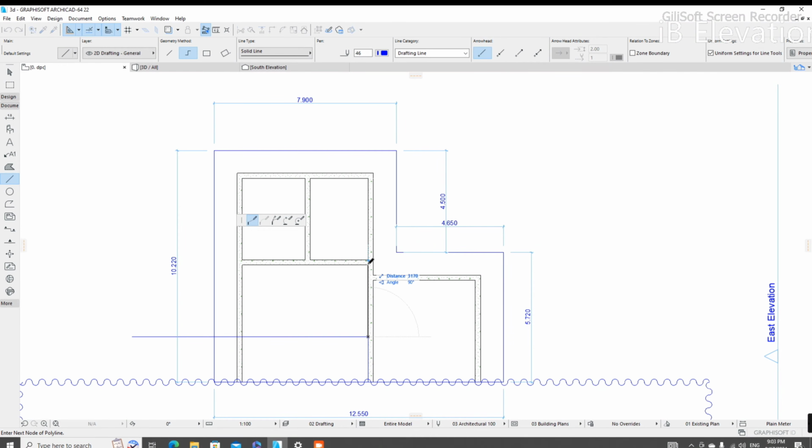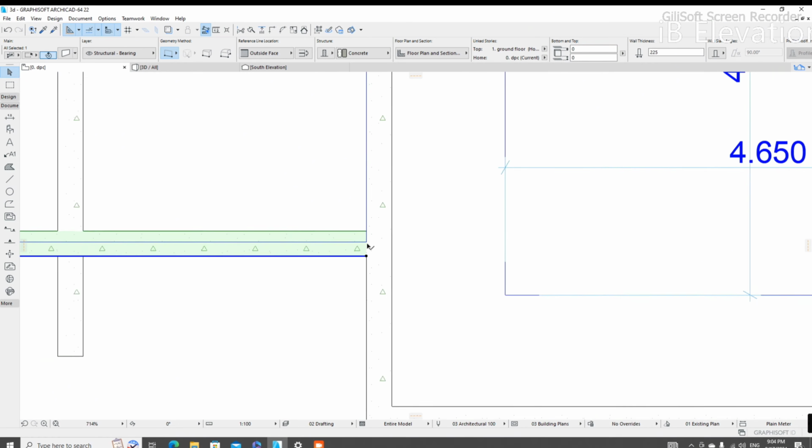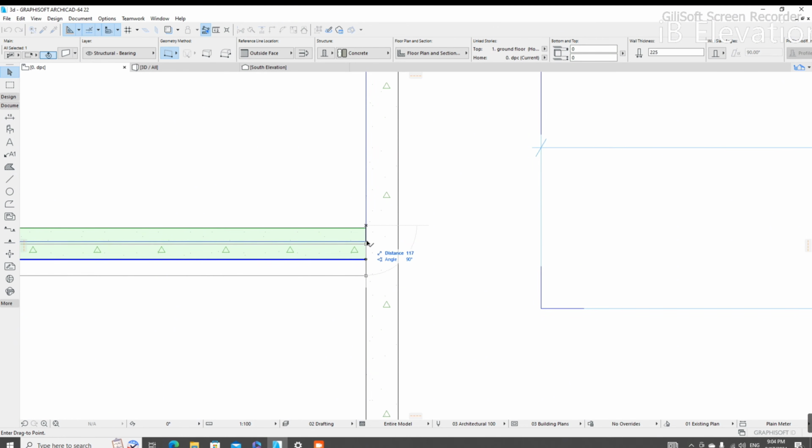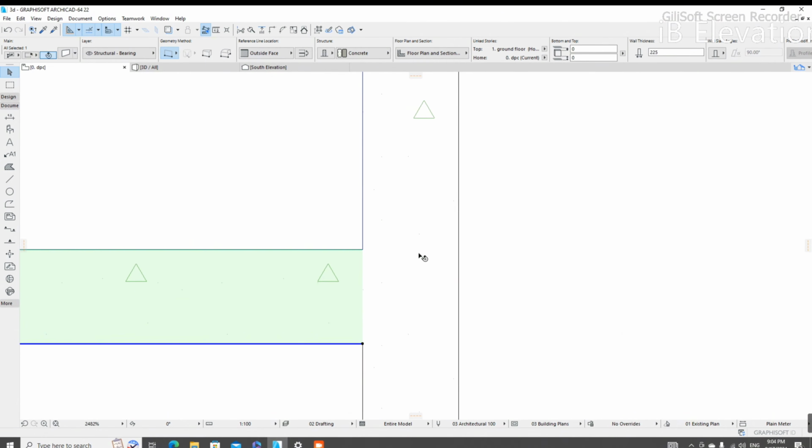You can see, if I have a 2-meter distance from the main road, I'll be left with 3.170, which is too small for the main lodge. So which means I have to rework my first calculated space to be 2.8 meter. Let's bring this to be 2.8 meter. Then let's move this backward to match 2.8 meter. Okay, now we have this to be 2.8 meter.